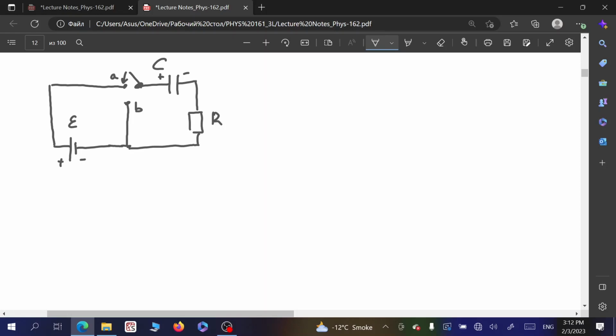We have a fixed amount of electric charge accumulated in the capacitor and two different resistors, let's say 100 ohm and 1 kilo ohm. For which resistor attached to the capacitor will it take longer for the capacitor to be discharged? With the high resistance? With the high resistance, it will take longer to discharge the capacitor. Why?